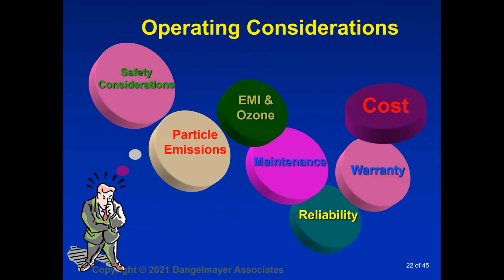So some of the operating conditions, certainly safety is a consideration. Is the ionizer safe? Remember, you are putting high voltage there, so you need to be concerned about how you are being protected from that high voltage. If you had a clean room, you might be concerned about particle emissions. Ionizers do make some EMI and ozone. They do require maintenance, and let me say this right out front.